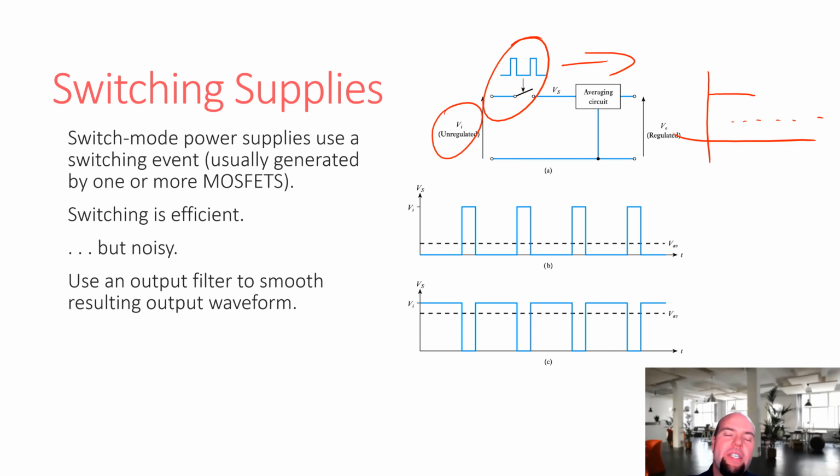And also that noise is more than just the signal. The noise matters more than just having a signal that has to be LC filtered or capacitively filtered. It also interferes with other things in your circuit. Switching supplies are notorious for interfering with analog signals. If you have a very sensitive analog signal, you probably want to keep it very far away from your switching supplies, because these supplies typically have a lot of current flowing through an inductor.